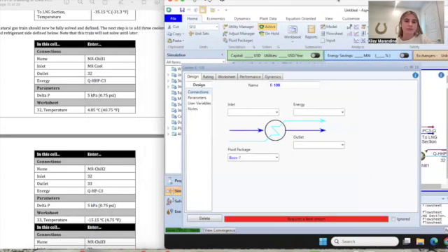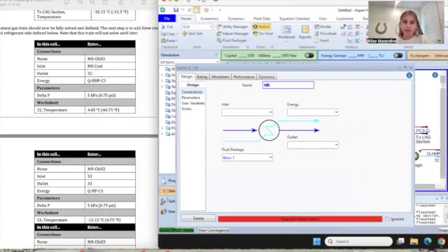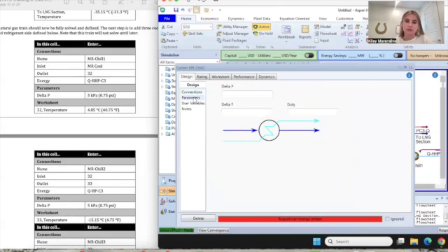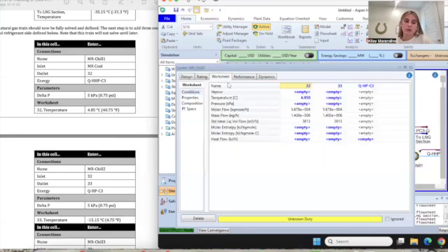Add another chiller, MR chill 2, inlet 32, outlet 33. Energy Q-HP-C3, delta P 5 kPa. Worksheet temperature for 33 is going to be negative 15 degrees.